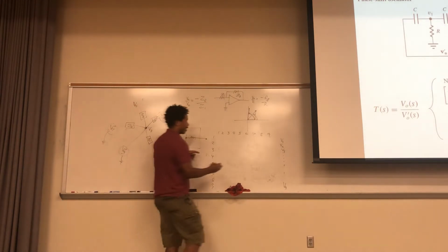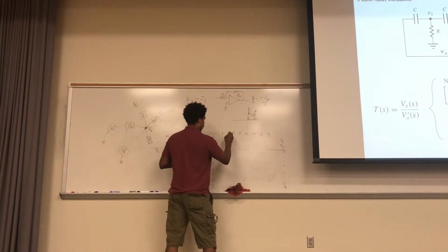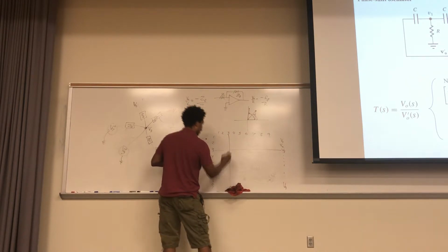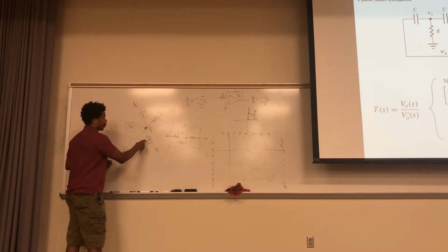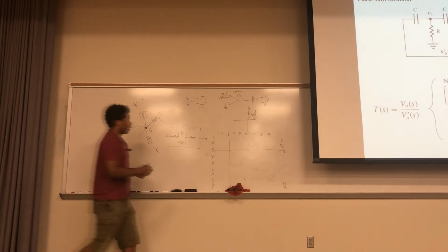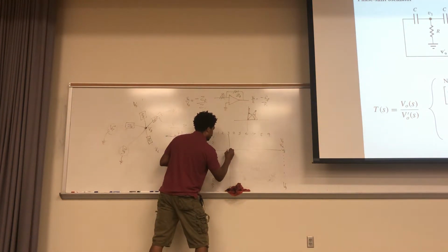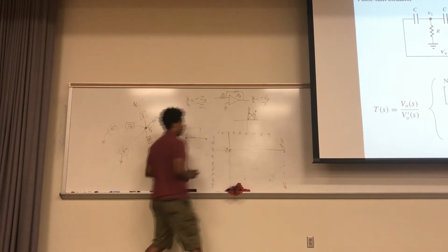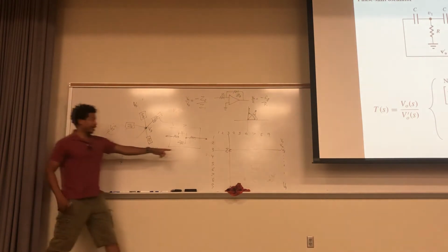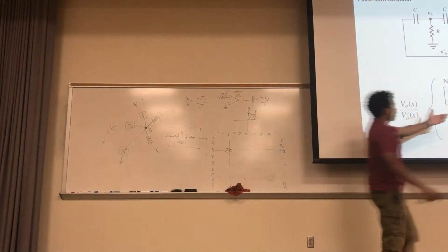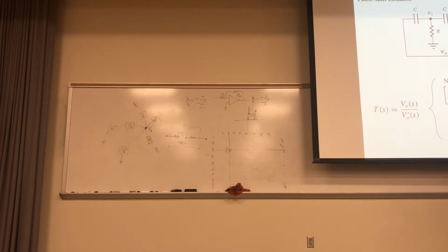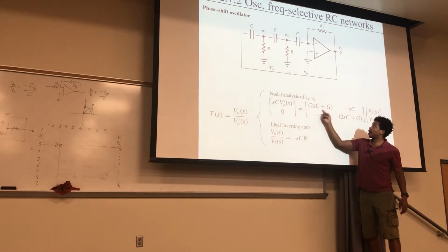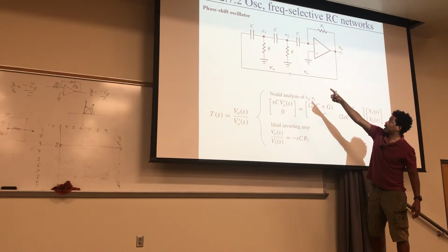So at V3, which is this row, this column, at this element right there, I have to add all my Z's together. Okay? So at this piece right here, I'm going to add all my Z's together. So I'm just going to say sum of Z's. Whatever my Z's are, I add them all up together, and I stick it right here in this matrix. That's what happened right here. So at that Z1, you can see it's surrounded by 2 capacitors and a resistor. You just summed it all up, everything connected to V1.